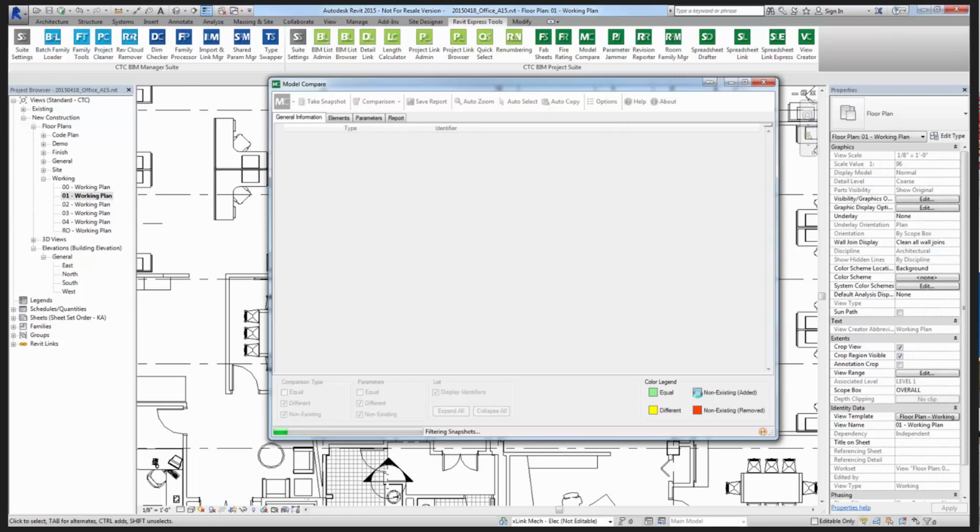But if I'm wanting to know what's inside that model, for example, have they drawn new walls? Have they drawn, and moved and erased ceilings and things like that? Well, for that, I have to open up their model and actually snapshot their model. So as I receive their model the first time, the first version, I would create a snapshot of that model as a part of my receiving process. And then as I receive the model the second time, I would snapshot it again, and I would start actually running a comparison on that and finding out what the differences were, to see if they're doing crazy redesigns or deleting of objects and recreating them or changing fire ratings of walls or information like that. I can find that out, but I have to run that on their model as opposed to running it from mine. My model will just tell me how that link has been modified within my model, the link's actual settings, not the individual objects.